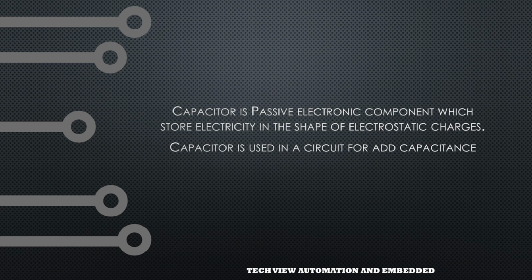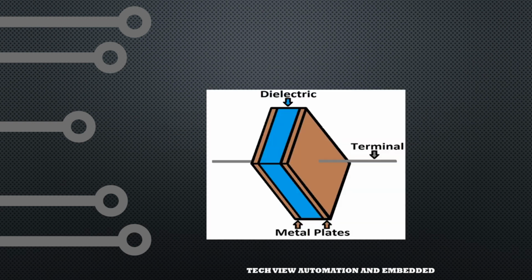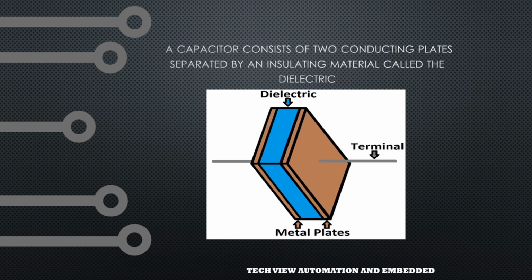There are many different kinds of capacitors available, from very small capacitor beads used in resonance circuits to large power factor correction capacitors, but they all do the same thing: they store charge. In its basic form, a capacitor consists of two or more parallel conductive metal plates which are not connected or touching each other, but are electrically separated either by air or by some form of a good insulating material such as waxed paper, mica, ceramic, plastic, or some form of a liquid gel as used in electrolytic capacitors. The insulating layer between a capacitor's plates is commonly called the dielectric.